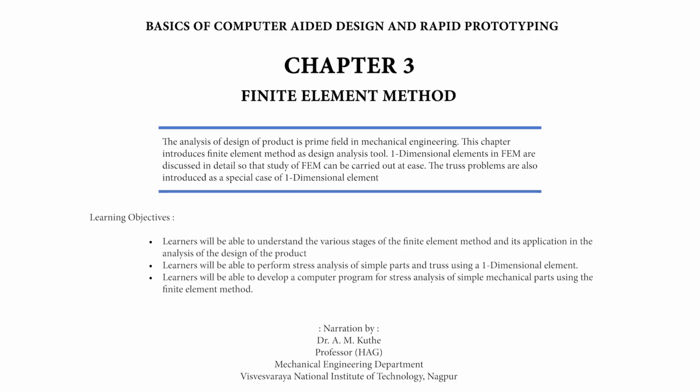In order to find cos theta and sin theta, the concept of direction cosines can be used. For the element, the direction cosines can be expressed in terms of L and M as L equals cos theta equals (x2 minus x1) upon LE, M equals sin theta equals (y2 minus y1) upon LE, where LE is equal to the square root of (x2 minus x1) whole squared plus (y2 minus y1) whole squared. It is clear that the direction cosines of the member can be found out if the coordinates of the nodes of the element are known.